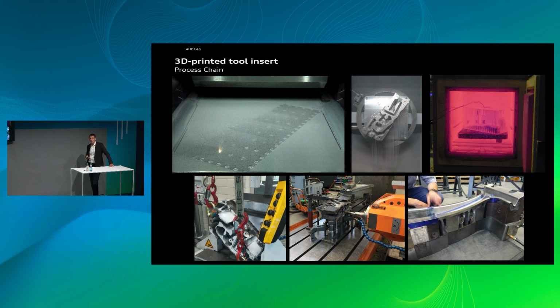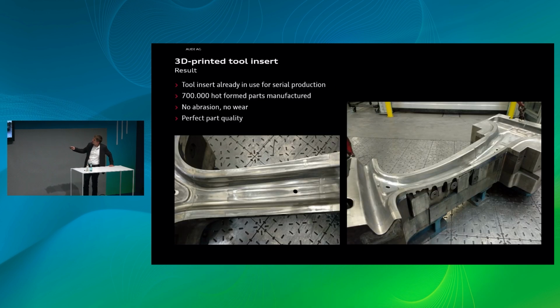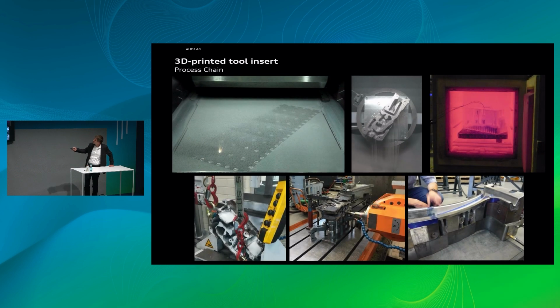First of all, there's a printing process. How to bring such huge and high volume parts to the printing machine. You see it here, it was really tough because of the distance between the build chamber and the surface of the build platform. So it scratched a little bit on the wall, due to the heat distortion of the process. And of course, this was the first try. We have to exchange the build chamber.